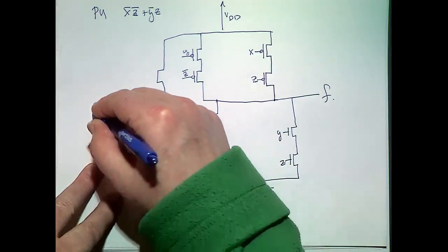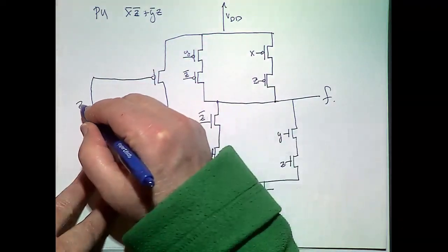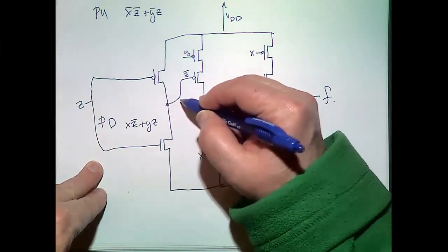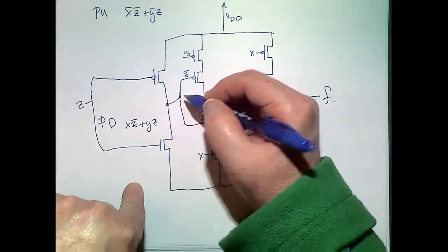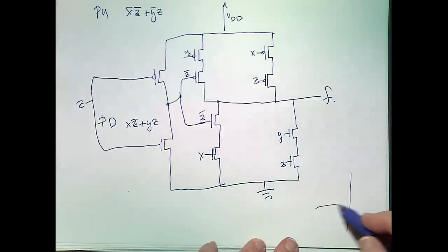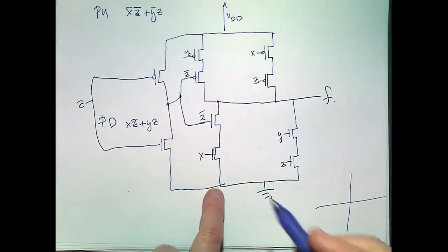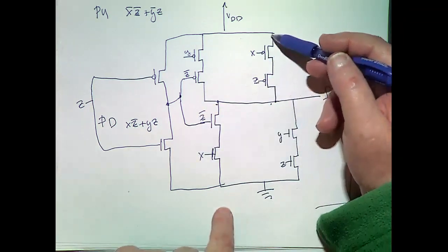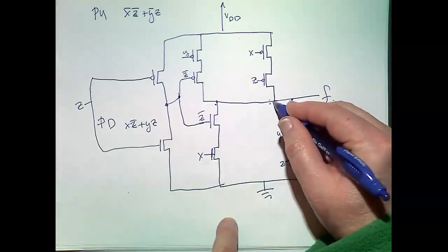Okay, I'm going to put that. We're going to go around this expression. Okay, and now I can connect to there. So we tend to put a little dot where wires connect. If you see two wires that just go like that, the assumption is that they aren't connecting. And that's why we try to offset these. So there's no mistaking that, for example, if these two had aligned up, you would have wondered, did it go through? Of course, the little dot should have been a tip-off that it doesn't.